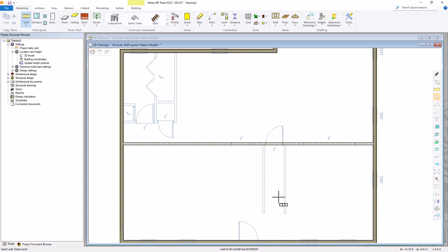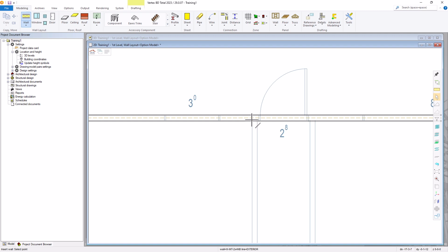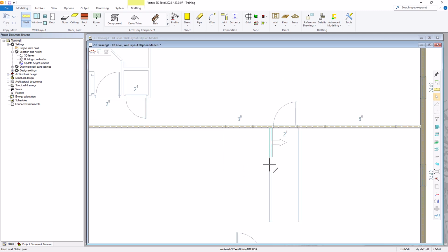Let's go ahead and select these walls here. I'm going to select this corner on that wall, lock it into vertical this time, hit I. Now you see that my wall is offset. It's not set correctly. So I'm going to right click, go to the opposite side, and now my wall is lined up. So I'm going to go down until I hit an endpoint, and V to confirm.